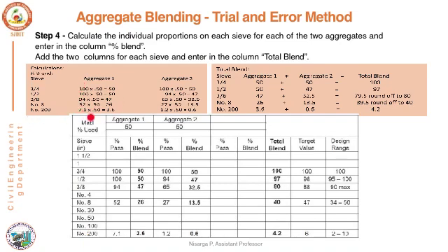The percentage pass of all these aggregates is multiplied by 0.5, and we have obtained the percentage blend as 50, 50, 47, 26 and 3.6 percent respectively. Similarly, we have done it for aggregate 2. All the values under the percentage pass are multiplied with the decimal value 0.5 to get the percentage blend.